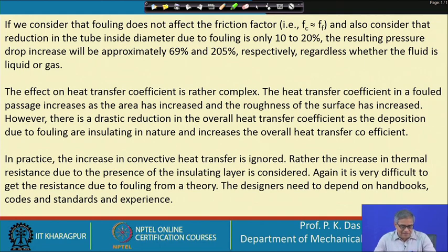In practice, the increase in convective heat transfer is ignored, rather the increase in thermal resistance due to the presence of the insulating layer is considered. Again, it is very difficult to get the resistance due to fouling from a theory. What will be the thickness of the fouling layer, what could be the composition, and hence what could be the thermal conductivity, all these things are not easy, almost impossible to determine.